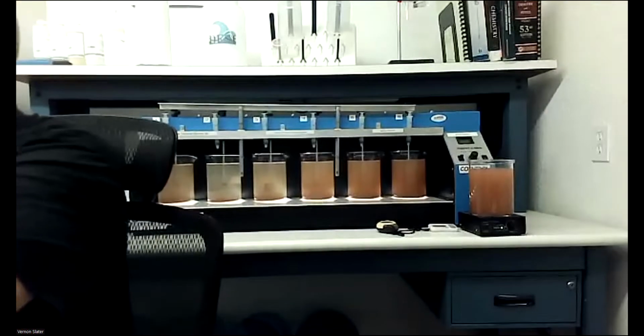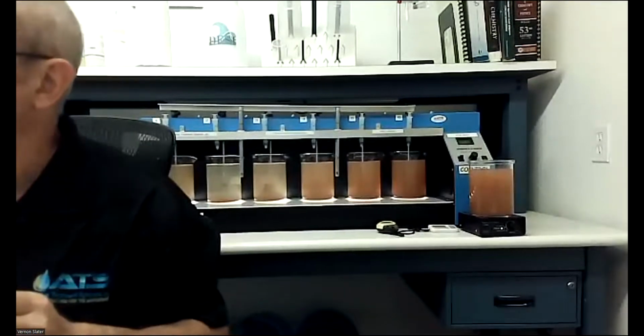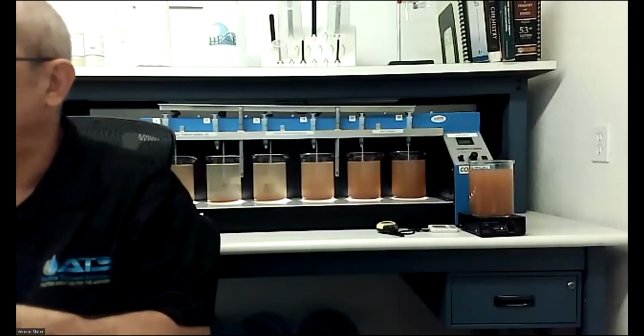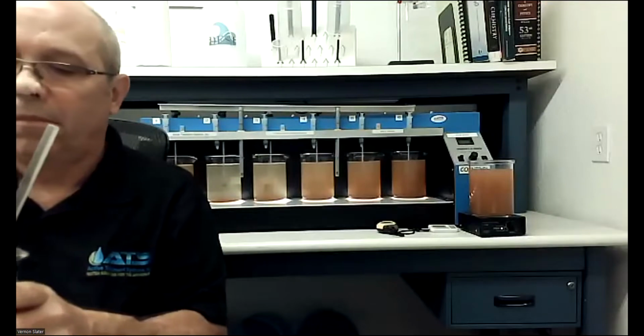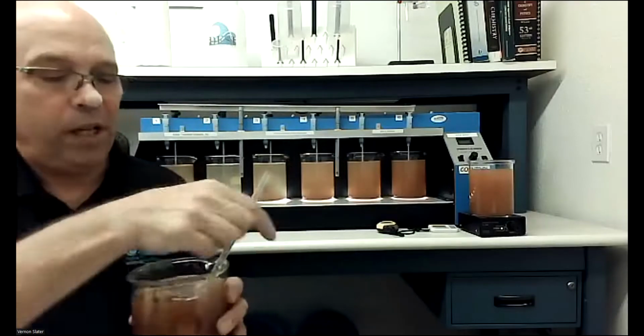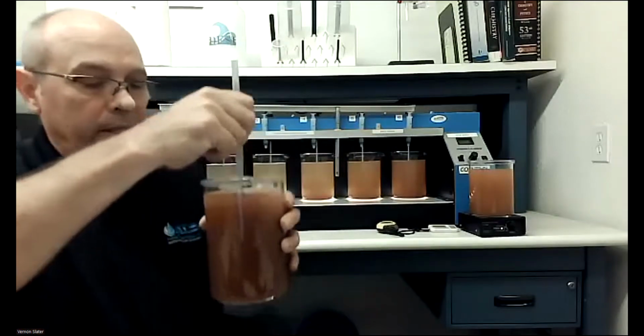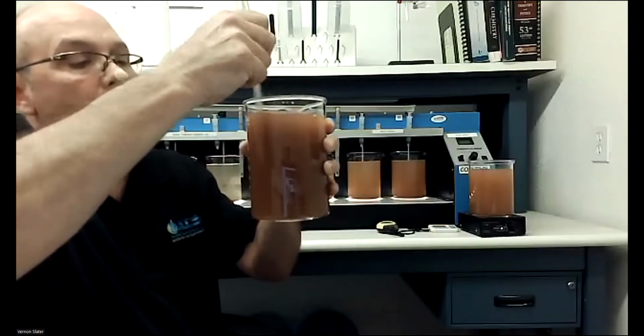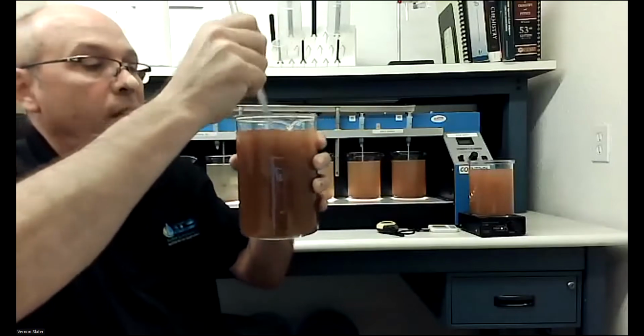And on site, you collect the jar like so. I'm going to get some polymer. I put in 3 drops. That is basically 50 milligram drops. They equal approximately 150 parts per million. So I might be slightly overdosed here, but I'm going to give this a shot with my mixing.